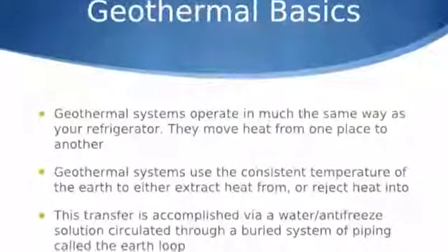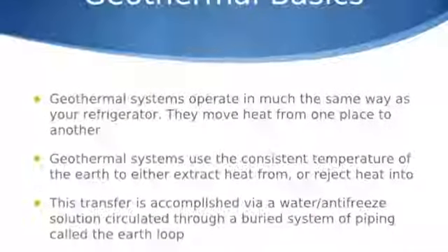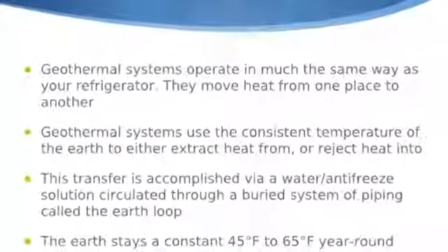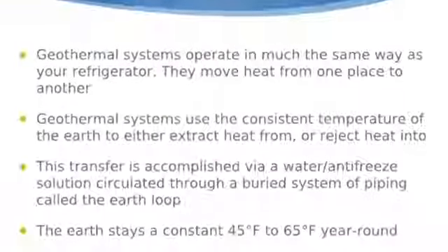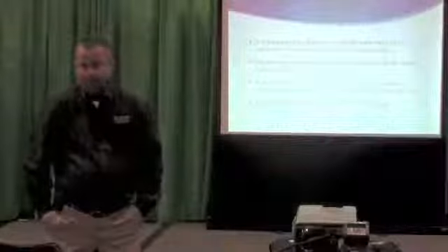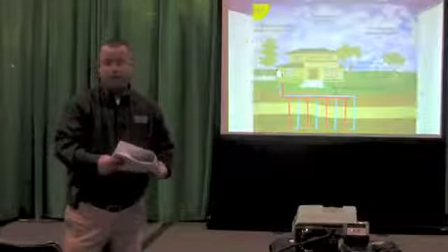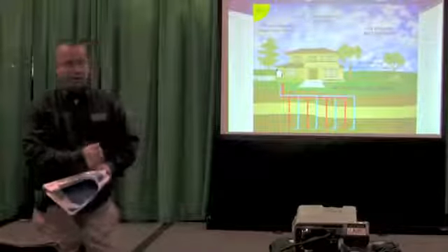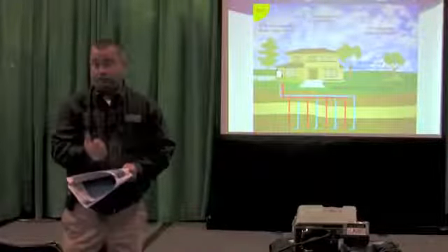In an air-cooled heat pump situation, we extract heat from the air outside in the winter and bring it into our home. With the geothermal heat pump, the water temperatures are going to be way more stable, between 45 and 65 degrees. So we can reject the heat into the water more easily, and we can extract the heat into the home. The heat pumps, as we know them today, are all equipped with defrost controls.